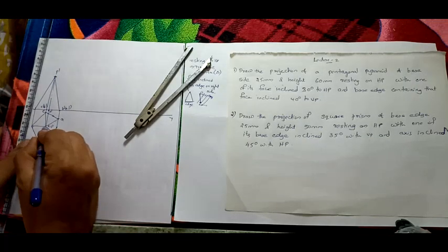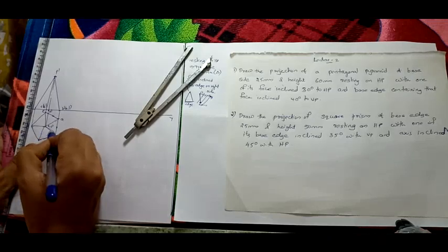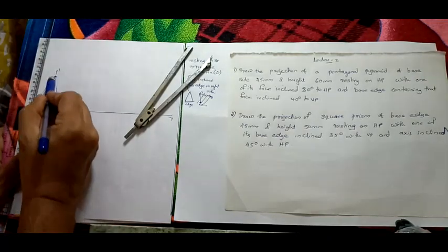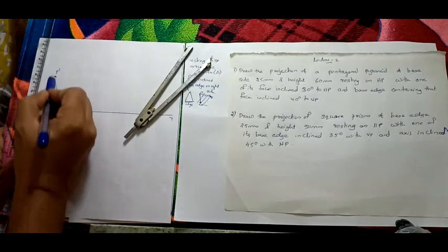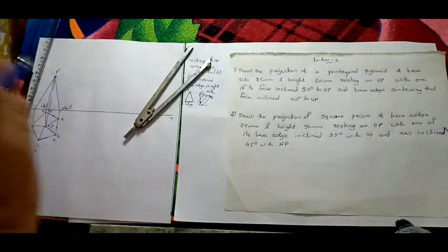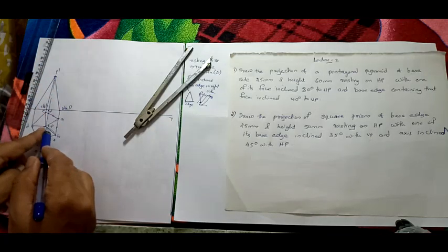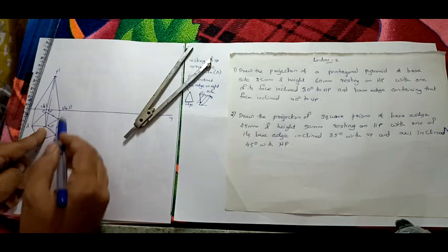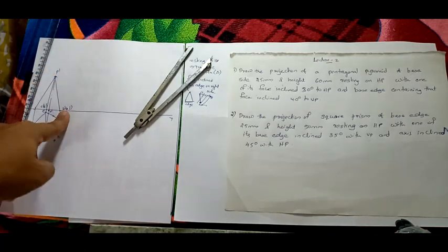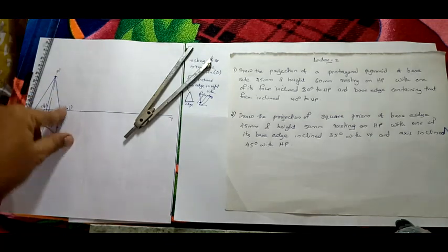See, this is your face on the right side, right? This triangle represents the face on the right side. That is represented here as a line. See, B dash A dash. This line is representing the face on the right side, right? So if you have a pyramid like this, this is your right side face, or this line, actually, is representing B dash P dash A dash. That means three points, so it's a triangle. So this is actually the face.